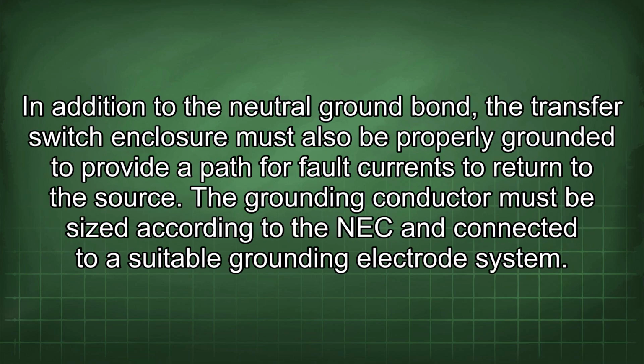In addition to the neutral ground bond, the transfer switch enclosure must also be properly grounded to provide a path for fault currents to return to the source. The grounding conductor must be sized according to the NEC and connected to a suitable grounding electrode system.